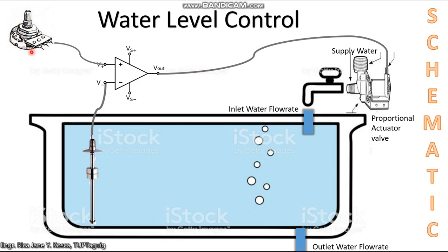Okay, so as you adjust this potentiometer, the resistance of the potentiometer changes, and the current provided as input to this differential amplifier will vary according to the resistance setting of this potentiometer, in which that resistance level has a calibrated level of water into it.